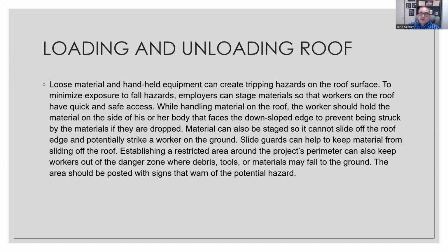While handling materials on the roof, workers should hold the material on the side of his or her body that faces down the slope to prevent being struck by material if it is dropped. So if you carry something behind you and it slips, it can kick your feet out from under you and create a fall hazard. Material can also be staged so it cannot slide off the roof and potentially strike workers on the ground. Slide guards can help keep this material from sliding off the roof.